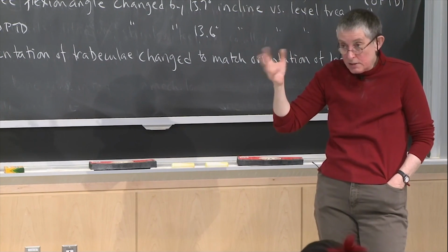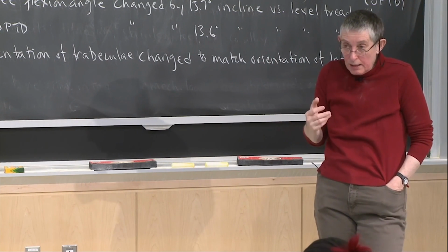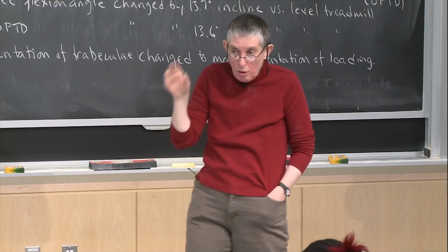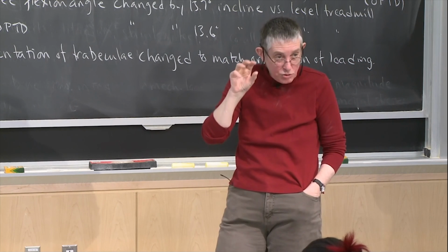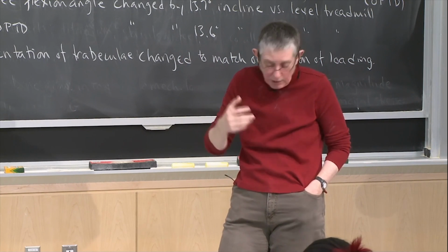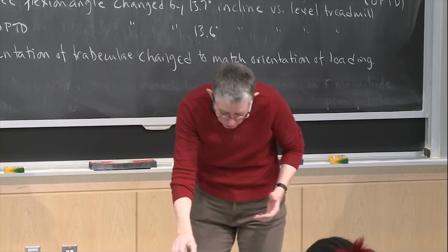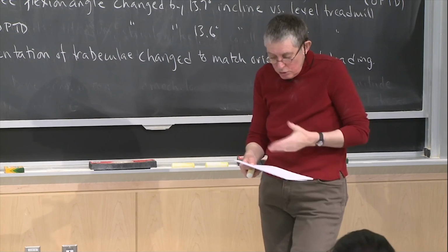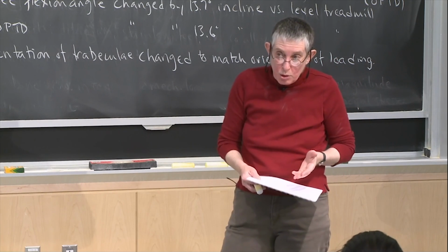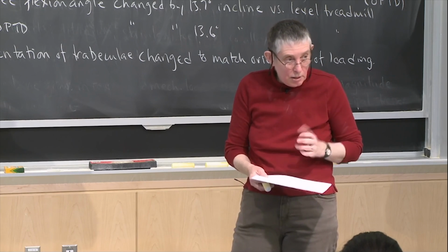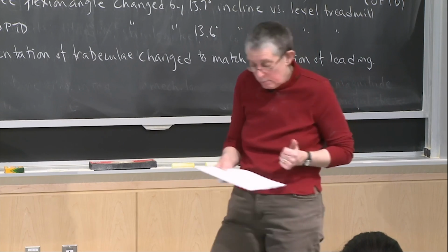So the finite element analysis is a sort of computer numerical analysis to do mechanical calculations. And if you know what the modulus of the structure is, you can back out what the modulus of the solid must have been from the finite element thing. And those sorts of experiments also showed that the modulus was around 18. And it turns out that moduli is about the same as cortical bone. And the properties of the solid trabeculae are very similar to the solid cortical bone.